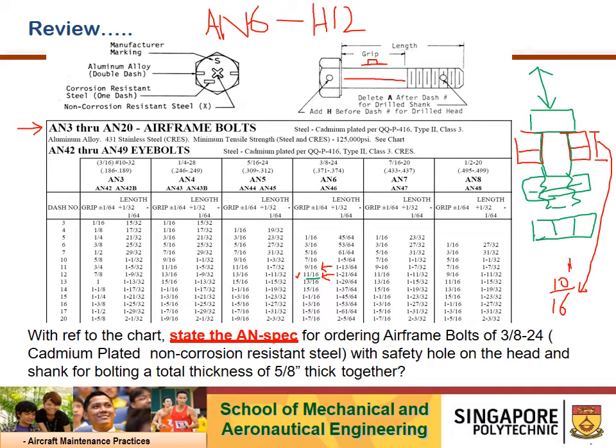So this is the part where the shank is exposed. If you were to leave it in this condition, your bolt itself will have a hammering effect, keep moving up and down because it's not clamping together. It's like a lateral movement, and this is not desired. So what can be added to solve this problem? We will talk about it at a later stage and let you think for a moment.